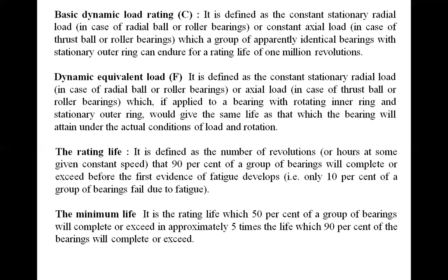So that is the dynamic loading condition. If a particular bearing, or a group of bearings, will take 1 million revolutions of life, then that is the dynamic load rating of the bearing.